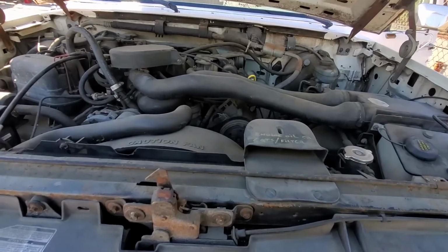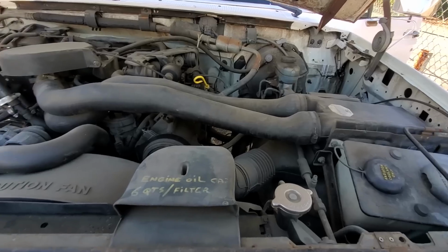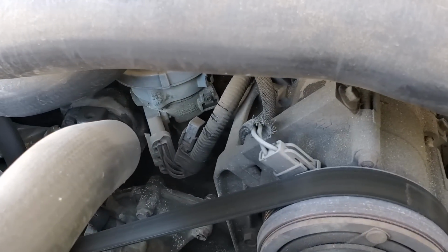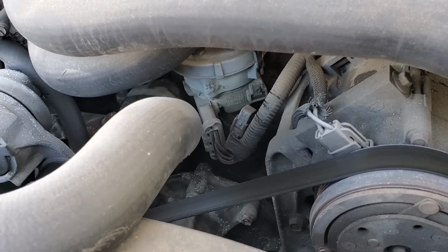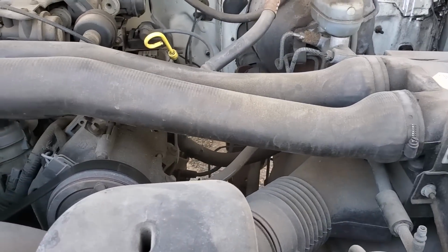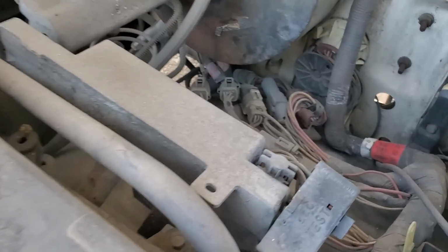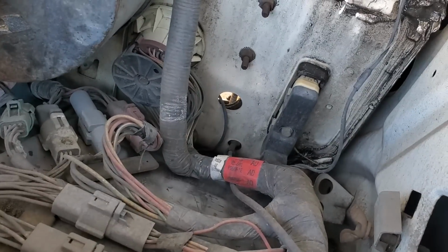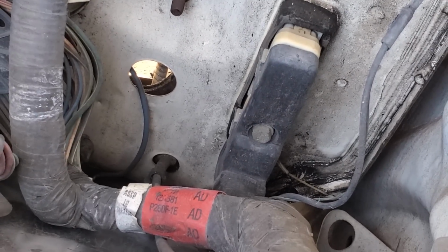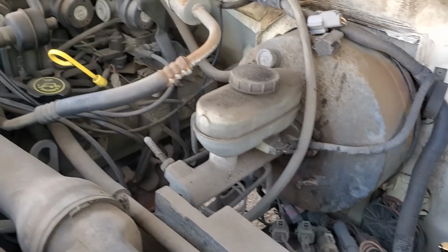Now the symptom here is sometimes it takes an hour to get this truck to start. And that can be a lot of stuff. That can be the ignition module, it could be the coil, it could be the distributor cap, the rotor, that could be the fuel pump. But since we know that the ECUs are a problem with these things, and it's right here in this particular truck, it's not that hard to get out. It's probably best we just pull it and inspect it before we go out.